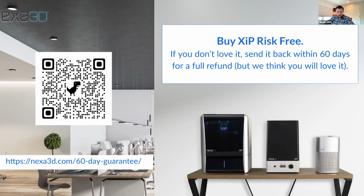I'm probably going to butcher this. Emma Line asks in the chat, are there any limitations on resin viscosity? I can tell you right now, I've used really thick resin before. Of course you've got to have the right ambient temperature, but even when a resin is incredibly thick, it's not entirely hard to clean up or anything. You don't really have a lot of limitations when it comes to the viscosity of the resin. Have you found any limitations, Sean?